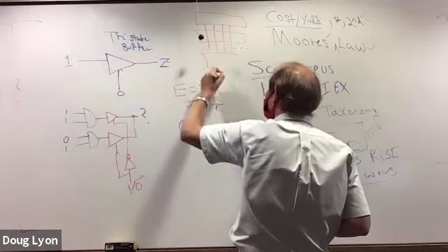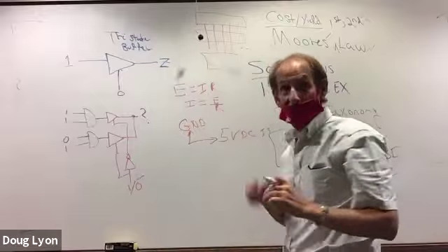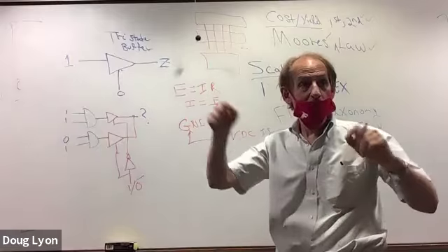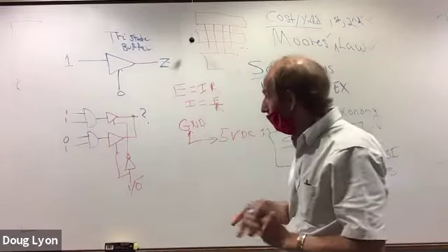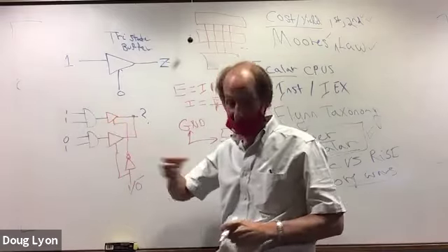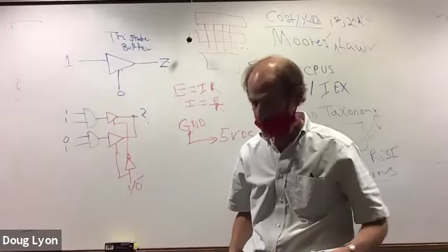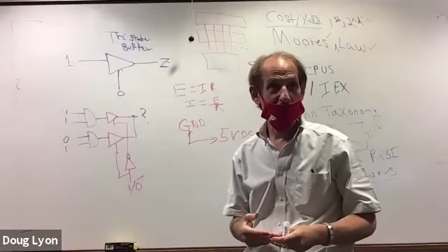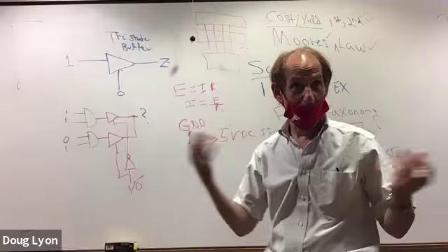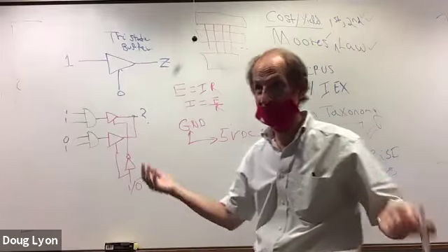All being driven by multiple cards. And you have to choose which card has control over the bus. If they all start asserting the bus at the same time, you're going to have a problem, because one of them is going to say, hey, that bus should be ground. And another one's going to say, nope, it's 5 volts. And it's going to go zip, and you're going to have a short, and you're going to blow out boards, like Tesla cards, big expensive boards.